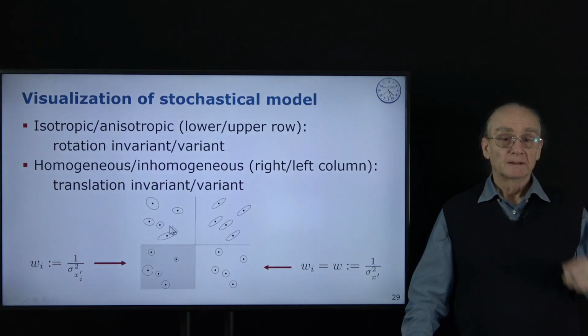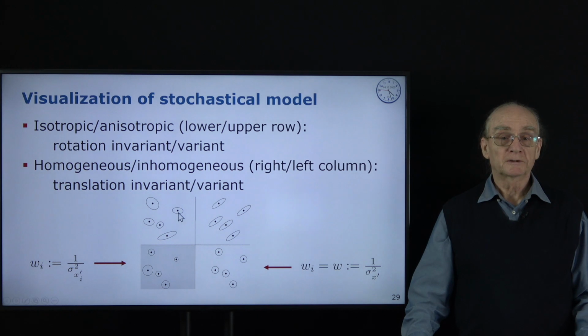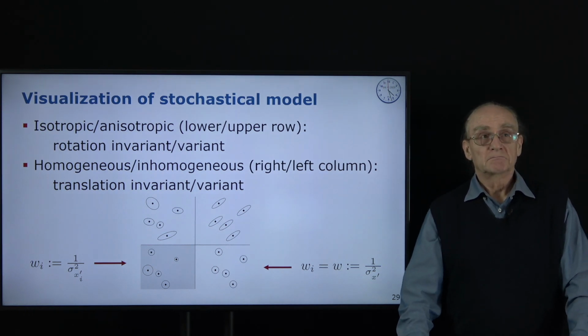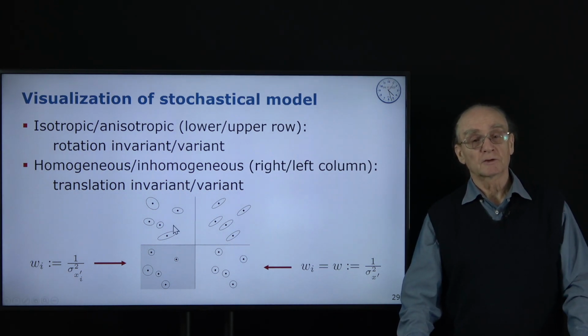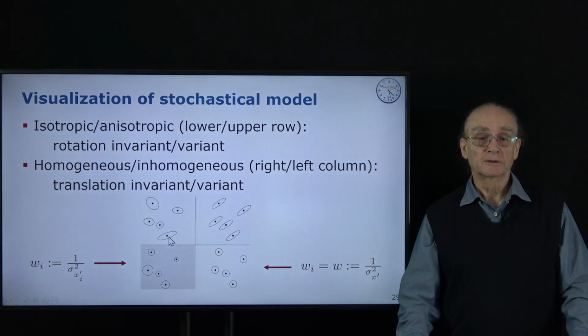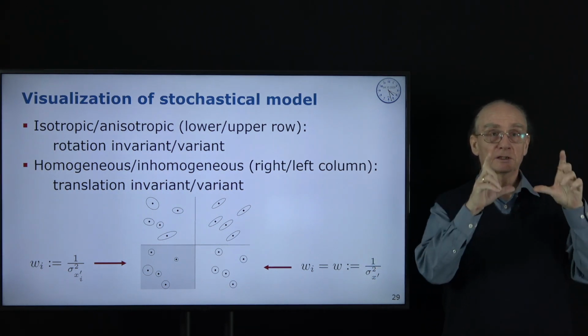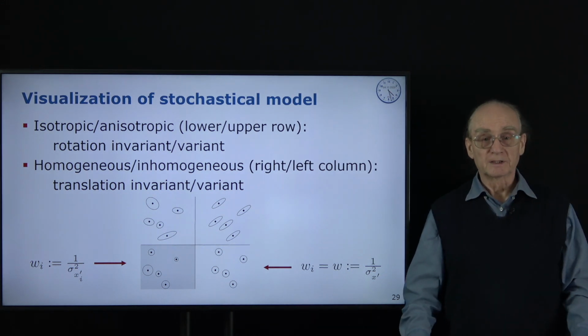Let's have a look. This would be a very general situation. So we have here 5 points, and each point has an individual standard ellipse here, here, etc. They're all different. They have different directions. They have different size. Even what I don't show here in the figure, they may be even correlated. So this would be the situation if the covariance matrix would be full. If the points are not correlated, so each individual point is independent of the next point, then we would have a block diagonal matrix for the covariance matrix. But each submatrix would be full and different.